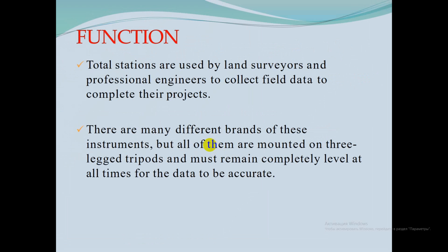First, total stations are used by land surveyors and professional engineers to collect field data to complete their project. There are many different brands of this instrument, but all of them are mounted on 3-legged tripods and must remain completely level at all times for the data to be accurate.